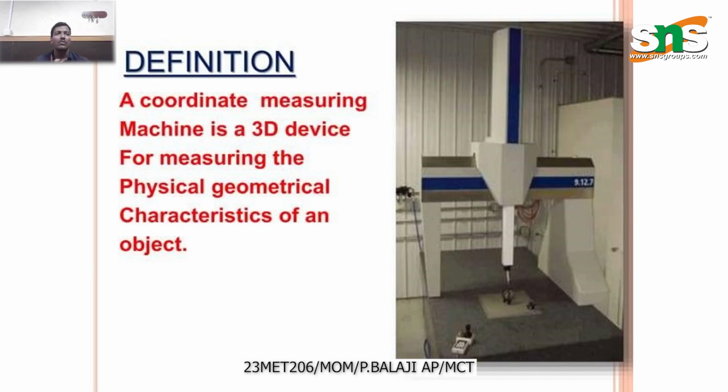Then you have to take the dimensions from the two-dimensional sheets, the 2D data, and you have to take the data from the CNC machine too. You have to combine those data with the data from the CMM. The CMM will compare its output to your CNC and 2D data, so precisely it gives us some output: how much it varies, and how much it equals the original data. Like you can see in the image,